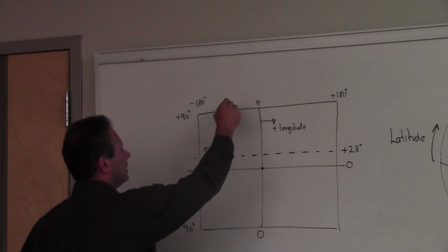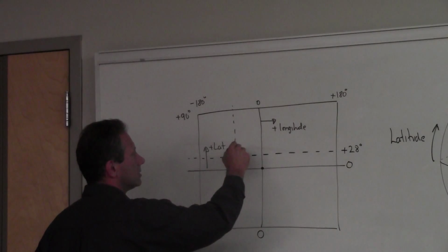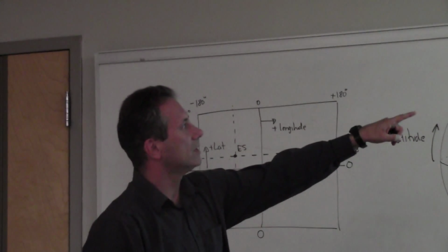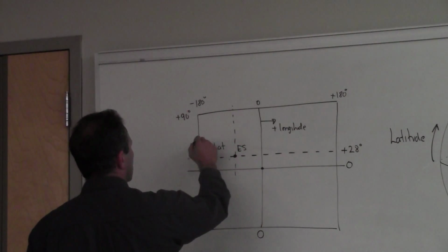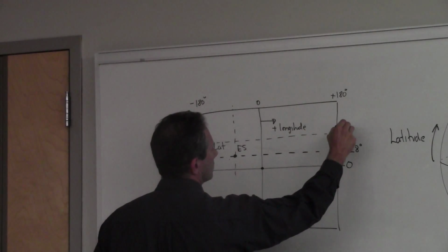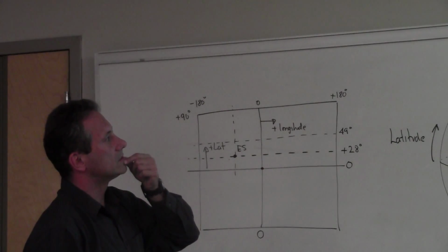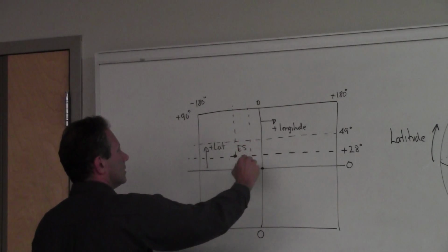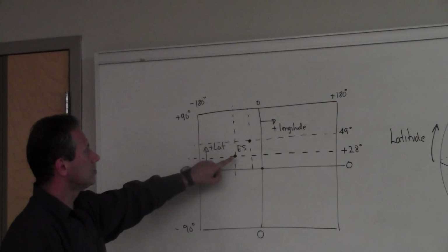And then we are 80 degrees west. So this is the location of the Earth station. The satellite itself is 49 degrees north, so it's somewhere here, and it is 48 degrees west, so it's somewhere about here, right? So what should be our azimuth?